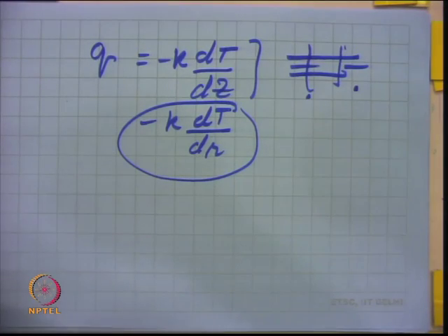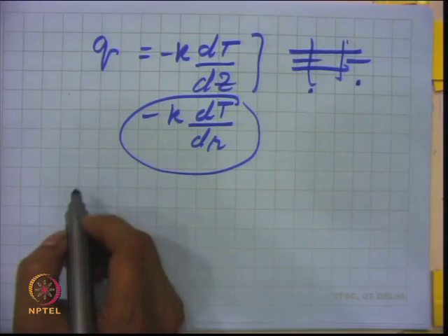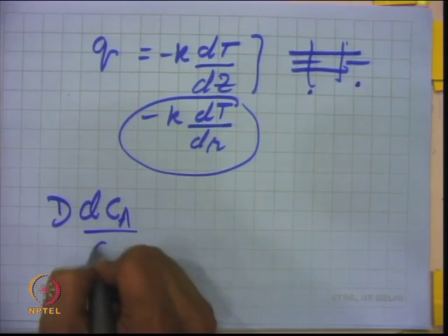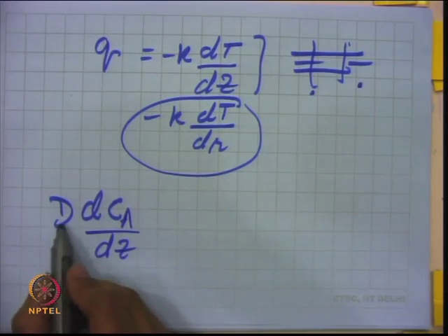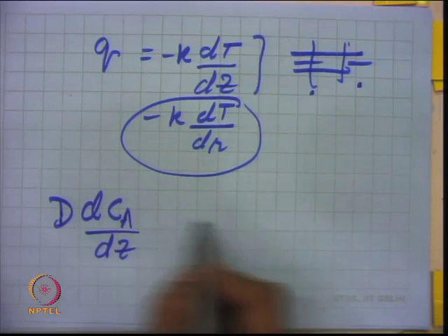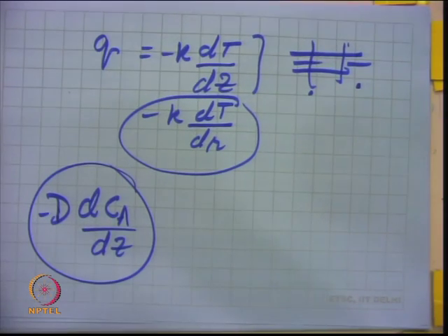Same thing, just like the axial dispersion term I mentioned, where you use Fourier's law analogy. The flow is because of dCA by dz in the z direction. This is related to a non ideal flow parameter, because this is a kind of dispersion in the direction of flow. It is one flux which arises because of the concentration gradient.